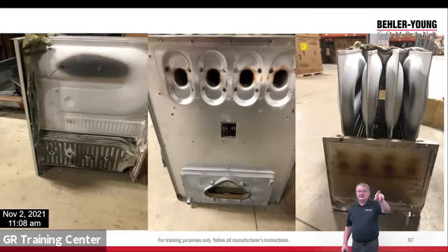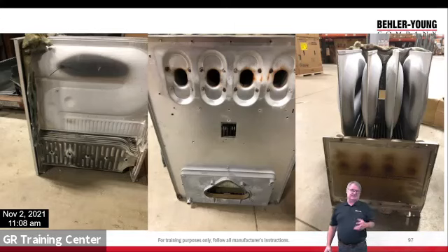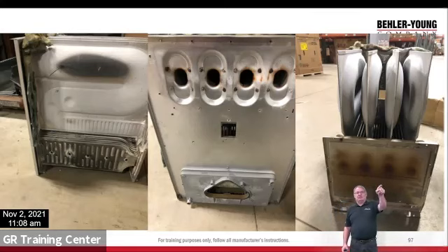So that secondary heat exchanger, the lower one, the flue gas is only going to be about 200, 250 degrees. And then that house air is going to blow across that first. We're going to squeeze almost all the heat out of there. So the gas coming out of this is about 100 degrees, gas and water. So again, the burner's at the top, goes through the primary, through this collector box above my head, into the secondary, out to the draft inducer and to the vent. All right. And we're squeezing almost all the heat out.